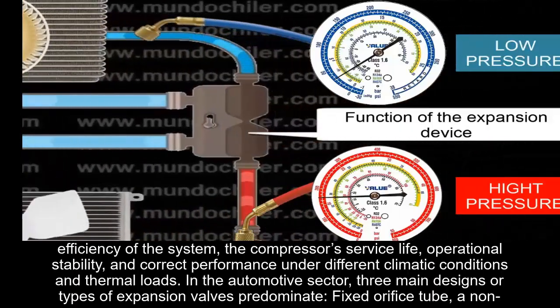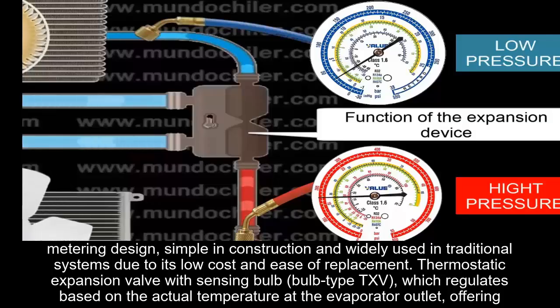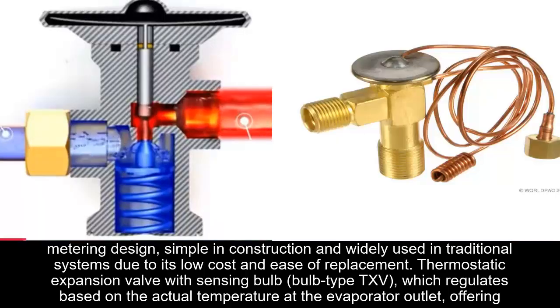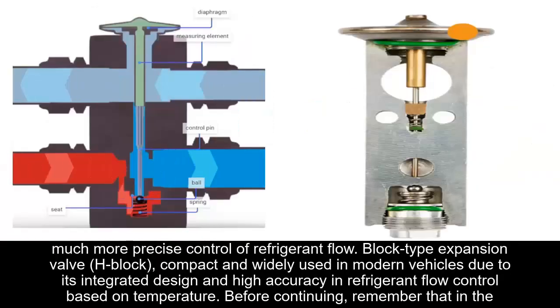In the automotive sector, 3 main designs or types of expansion valves predominate. Fixed orifice tube, a non-metering design, simple in construction, and widely used in traditional systems due to its low cost and ease of replacement. Thermostatic expansion valve with sensing bulb, bulb type TXV, which regulates based on the actual temperature at the evaporator outlet, offering much more precise control of refrigerant flow. Block type expansion valve, H-block, compact and widely used in modern vehicles due to its integrated design and high accuracy in refrigerant flow control based on temperature.